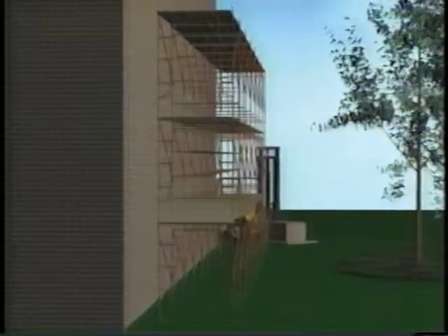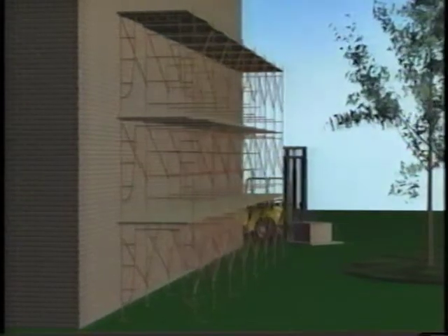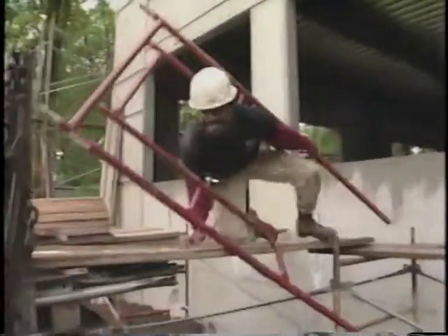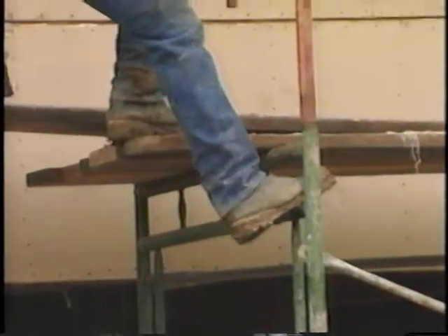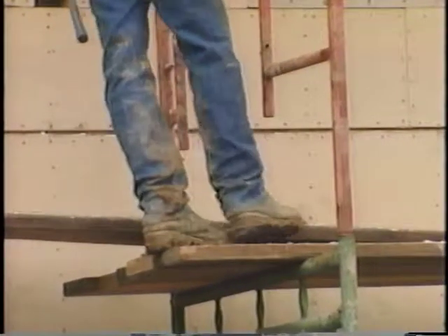Environmental conditions such as wind, lightning, and precipitation can affect your safety on a scaffold. Work should be suspended and all workers should get off the scaffold in high winds and lightning storms. Extra precaution is required on wet, slippery surfaces. Mud can also cause additional hazards and should be cleaned off.